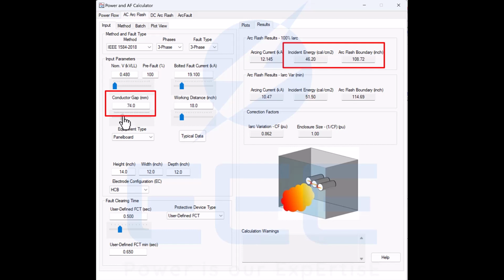This really matters because when we replace equipment with a different manufacturer, we often do not even look at the gap. When your ABB breaker is replaced by an Eaton breaker, all the nameplate data may have matched, but hold on, your conductor gap changed. Hence, your arc flash label is no longer valid even though the nameplate remains nearly identical. I caught flaws like that in some facilities.